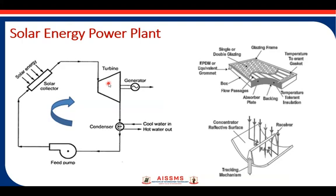Here the pressure energy of the steam will be converted into kinetic energy, and inside the generator the mechanical energy of the turbine will be converted into electrical energy. The steam will lose its pressure and temperature, and at the output of the turbine we will have a mixture of steam and water droplets.